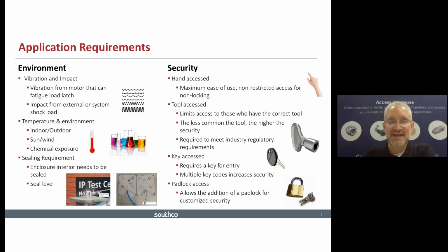Or will your application be seeing either chemical cleaners or chemicals themselves and need to withstand that kind of corrosive material? And more importantly, really, sealing. For latches that are on the inside, sealing is really not that important. The materials could be chosen which are a little more economical and not need to withstand corrosion or keep out the outside. But if your latch is outside and is subject to high winds and driving rain, sealing becomes very important as a consideration.